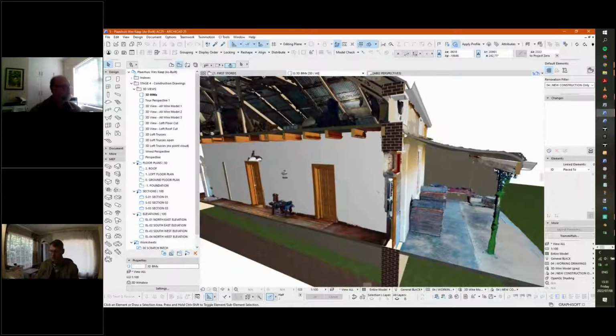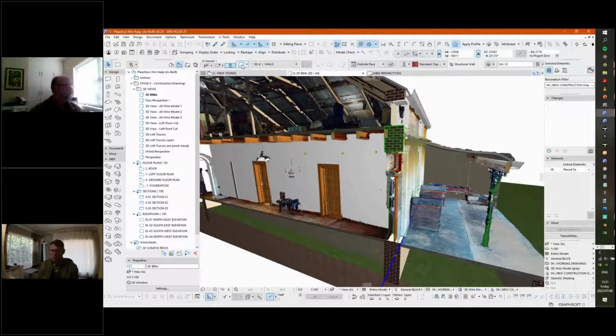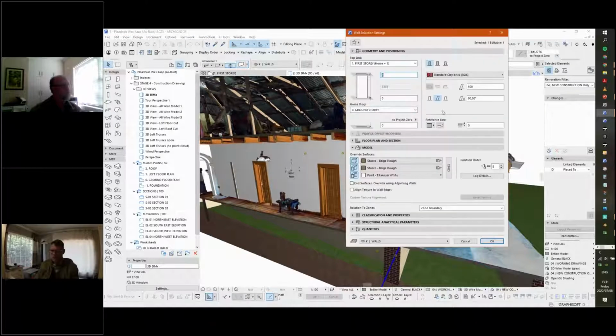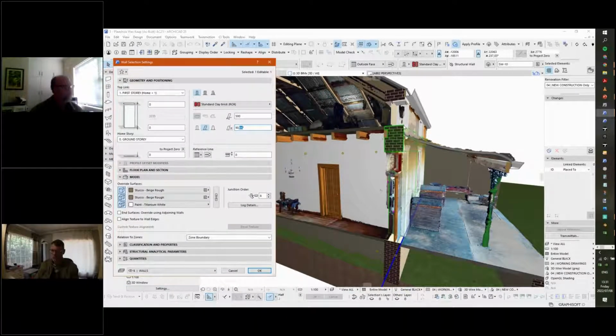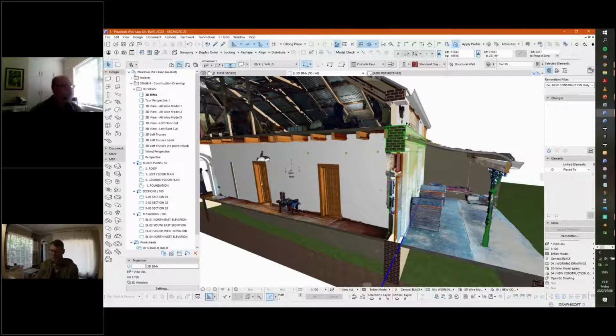But what you don't see with a clear eye is that this wall is actually leaning over. As you can see here, the wall is leaning over by 0.86 degrees, call it 0.9 degrees, nearly 1 degree lean. Also to note, this wall is only going up to the loft and ceiling floorboards. This client wanted to renovate and upgrade the roof space to become usable rooms, and we needed to model this accurately. And if I change this to an upright wall, you'll see that wall move to the outside.